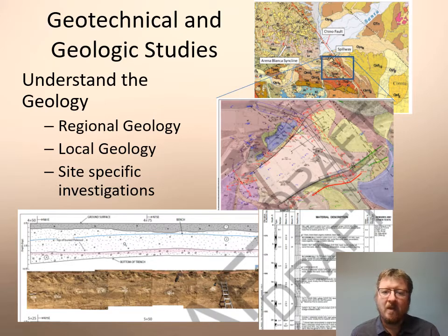So this is Prado Dam down in LA. They're working on the spillway down there, and this shows the regional geology map in the top part, and then on the bottom we have site-specific investigations where they did geologic trenching looking for faults and geologic formations, and borings to identify the different types of soil materials and test them for engineering analysis.